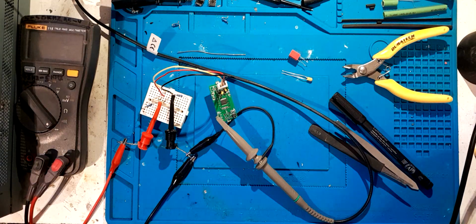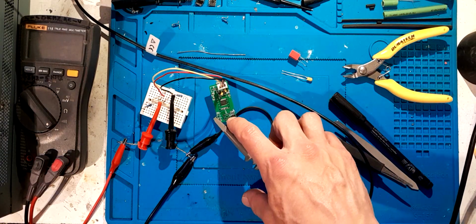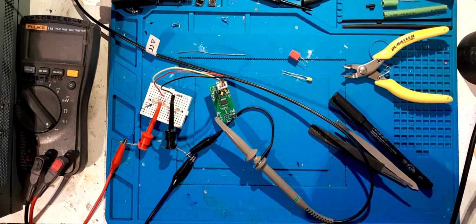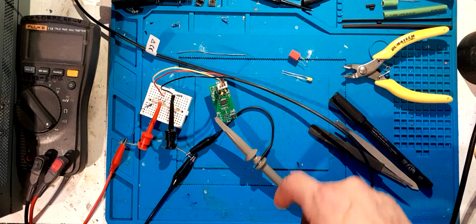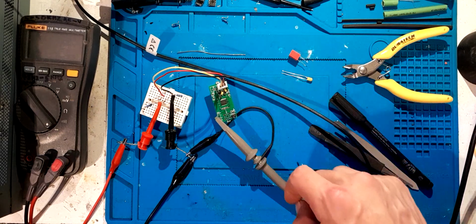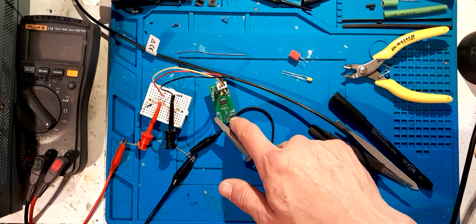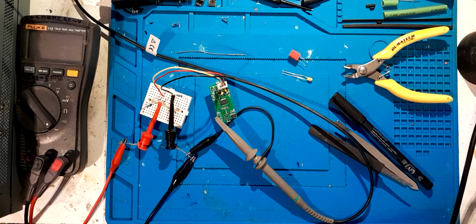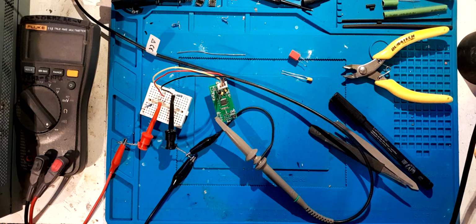So just to play it on the safe side, I'm going to put a diode pointing back across the regulator, so that on power down, when I put 47 microfarads of capacitance there, I don't get a reverse breakdown voltage through the regulator. So I'll go do that now. I'll go grab a 1N4148 diode, and another 3 10 microfarad capacitors, and I'll be back in a sec.